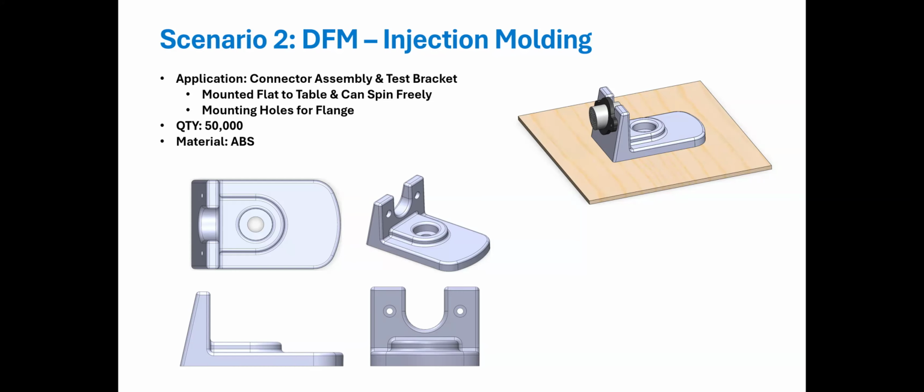is a requirement when designing any injection molded part. Ted says missing drafts. Correct. Incorporating draft into the design is the other. There is one more. You did guess this earlier. Yeah, that looks like it's going to need some side cores on either side. Correct. So it will need a side core when it's going to be molded.